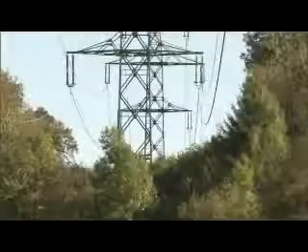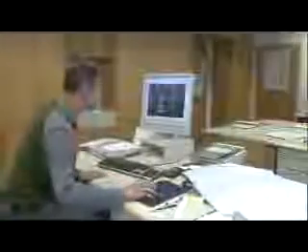Until now, the K factor has been calculated from system data. This calculation is problematic if the topography of a line is complicated. Parameters such as the height of the conductors above the ground and the soil resistivity can have significant influence. For older cable installations, some of the parameters required in the calculation may simply be unknown. Due to the large number of different parameters required and the difficulty in obtaining data, the calculation can be error-prone.